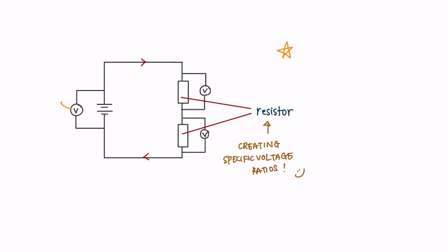Let's say I have a voltage in, or the voltage supply, of 9 volts. And according to my resistors, if I have 2 ohms here and I have 1 ohm here, I am looking to divide my voltage to each of these resistors accordingly based on its ratio. So the ratio here is 2 to 1. So the voltage out here would be 6 volts and the voltage out here would be 3 volts. So you just need to split the voltage according to its ratio.